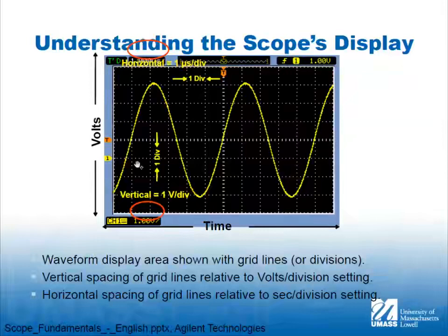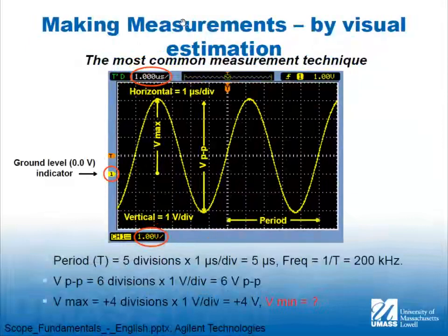Okay. Our vertical resolution in logic is 1 bit. It's above a threshold or below a threshold, and that corresponds to a 1 and a 0 respectively. Okay, so we can visualize this. Scopes have the ability to put up cursors, and they'll make measurements too in a minute. So the peak-to-peak voltage, the period is interesting. When we talk about logic analysis, we're not necessarily talking about a period, but we're talking about how much time between two events. So these measurements are going to carry forward.